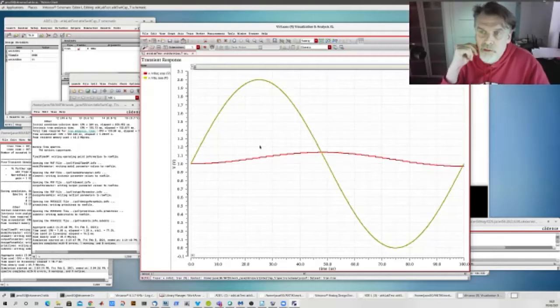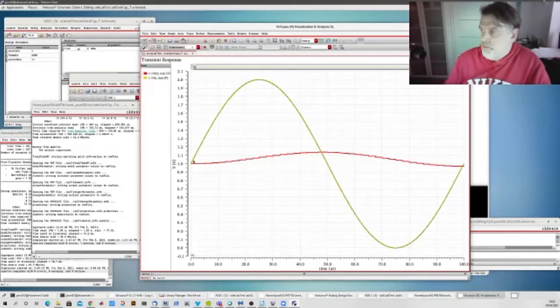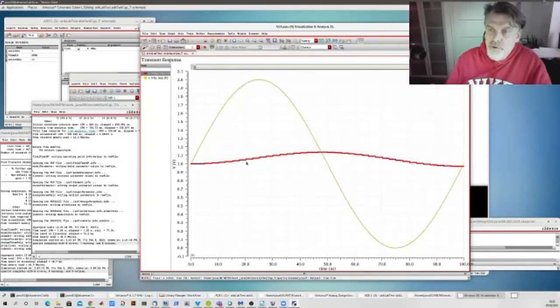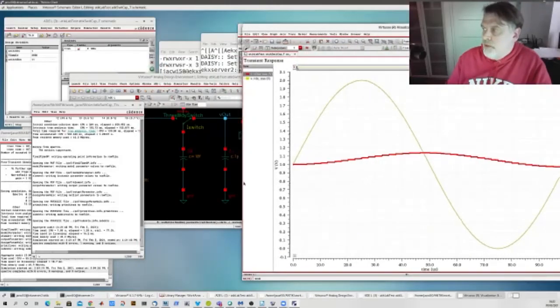And now you see we attenuate the signal quite dramatically. And the phase shift is almost 90 degrees here. You see you have a minimum here and a maximum at the zero transition here. So we're almost down at cosine, so we're almost at 90 degrees phase shift. So we have rolled off all the way beyond the pole. So we see quite clearly how it works.